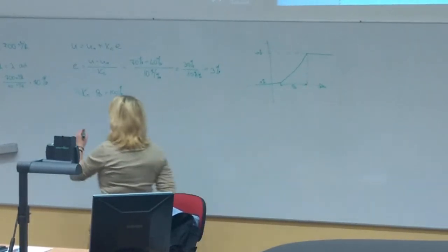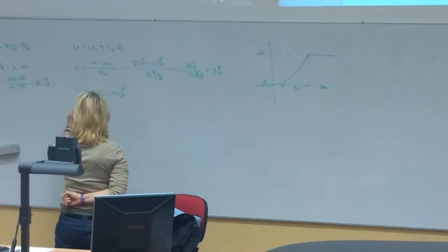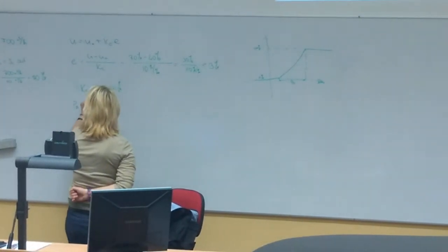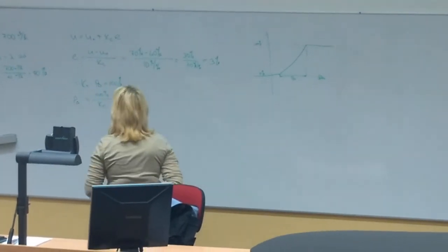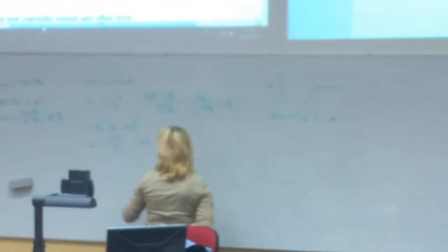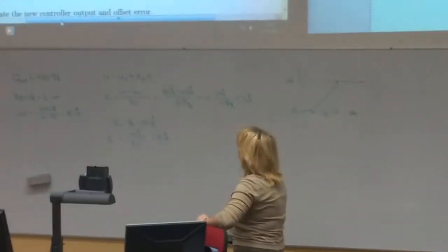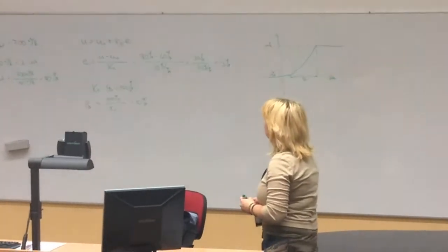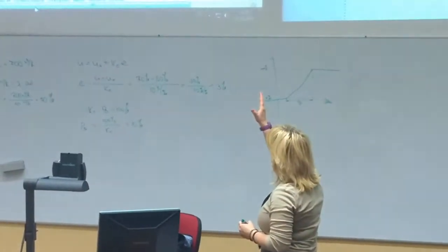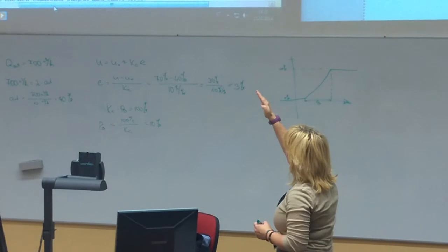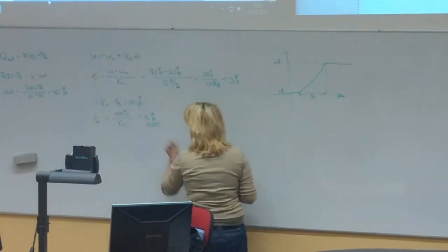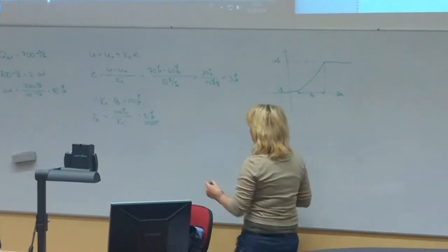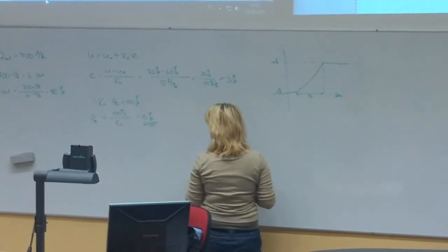Proportional band equals 100% divided by Kc, and in that case, it will be 10% of something. Basically, that means that because we would like to control the valve well, those 10% will be, for example, the angle of our valve.